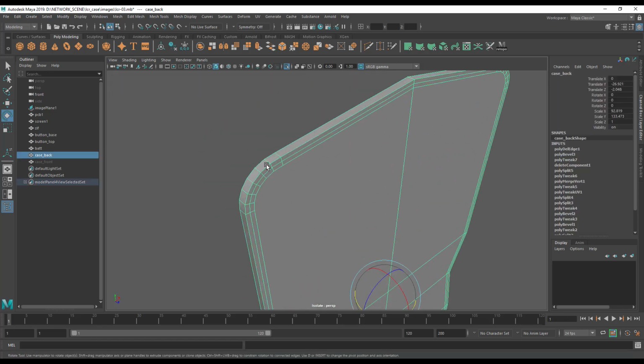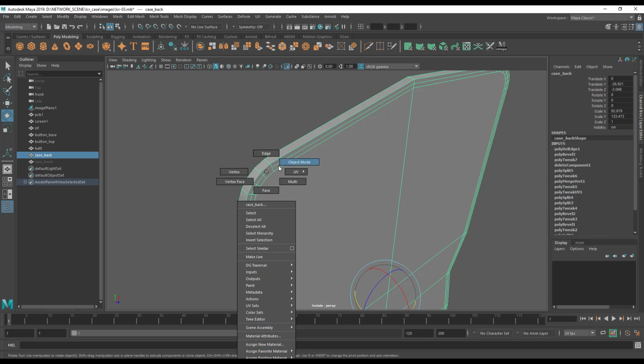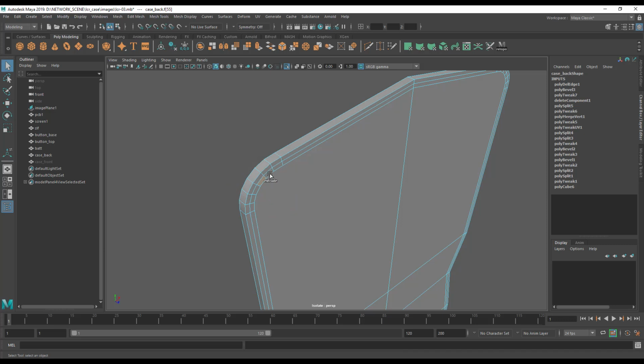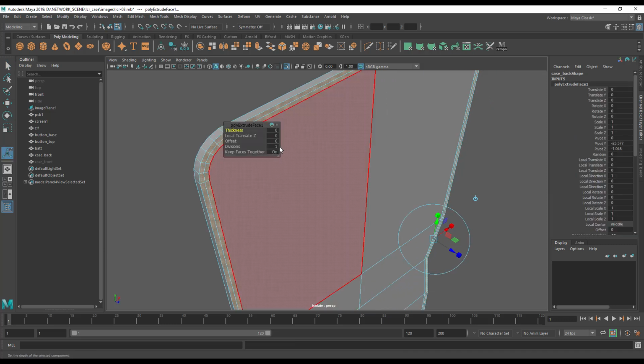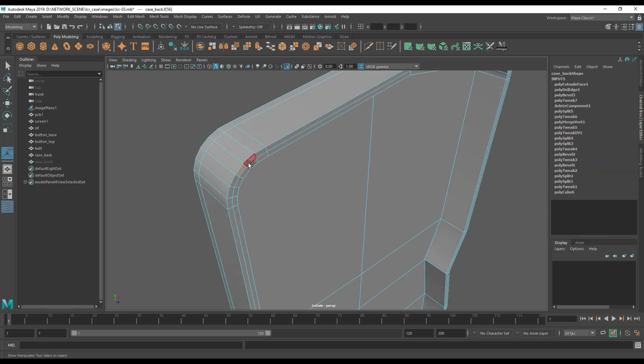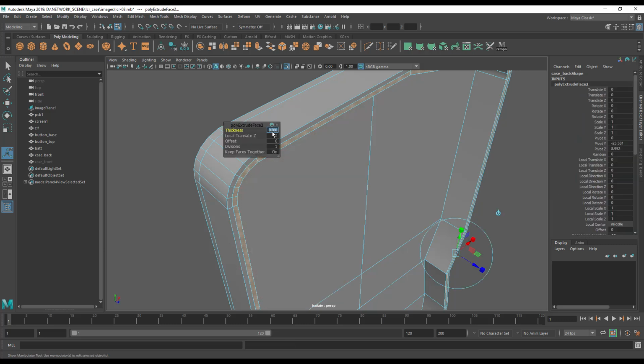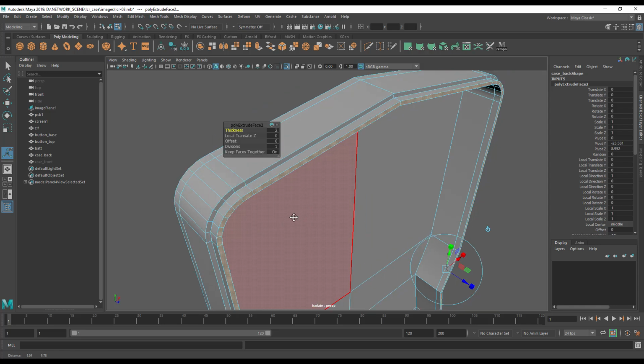So let's actually extrude this out now to a, let's see, select the faces. So click one, double click next to it, Control E for extrusion. Let's actually extrude it out to 10mm. Let's come in here, and which one do we want? This one, Control E. Let's extrude this out to 2mm to act as case lock.